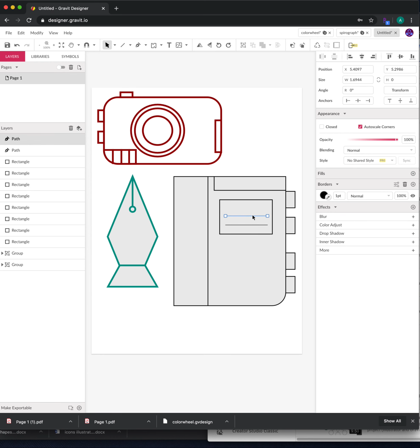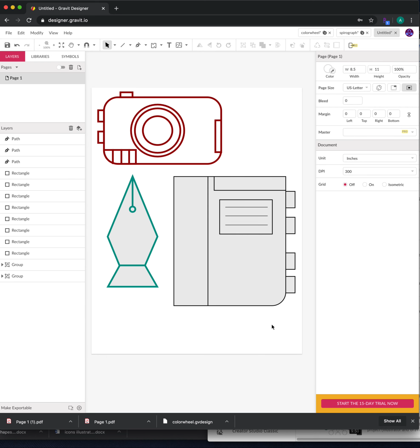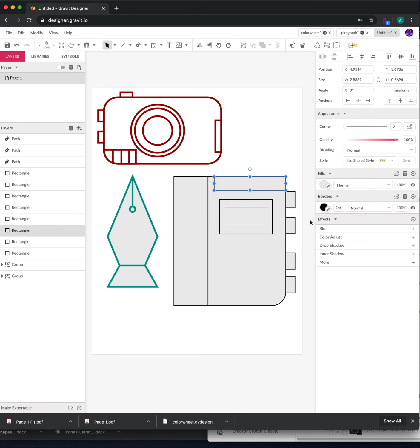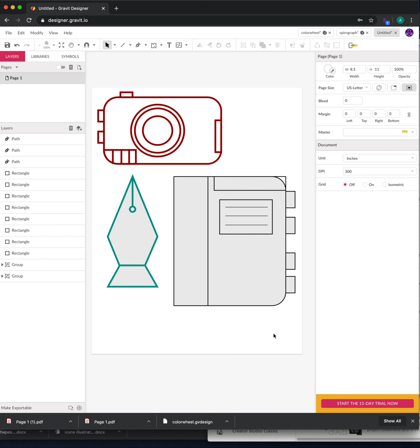And I'm using my Alt drag to create copies, because that's always easier than drawing new items. And now that they're here, I'm ready essentially to address this front corner. This is going to be easier to do if this object that I have drawn doesn't have a fill. So I'm going to set the fill at 0%, and I'm now able to see it. And I'm going to zoom in so that I can really tell what the heck's going on with that guy.